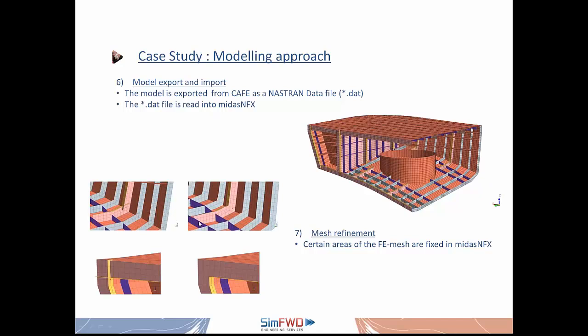As you can see here, there are some connection refinements between the stiffeners that need to be done, and this is done here within Midas NFX. Of course, there are several functions like merging, repairing, and also refining the mesh if needed. And you can see here some differences between where the mesh had to be fixed and refined.